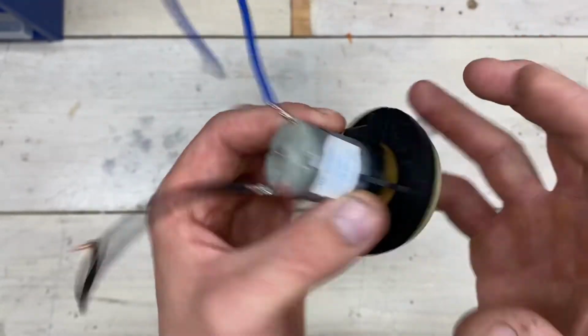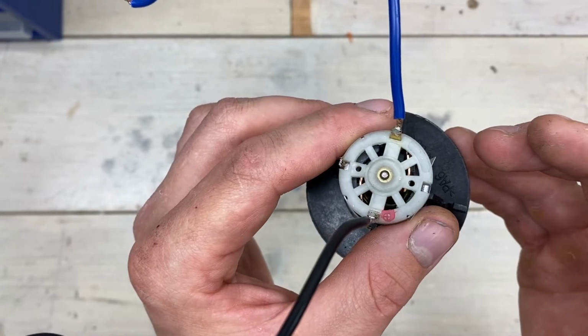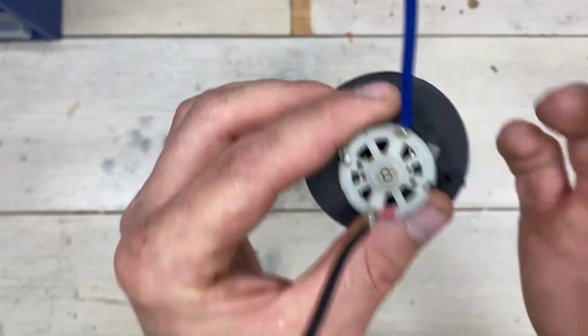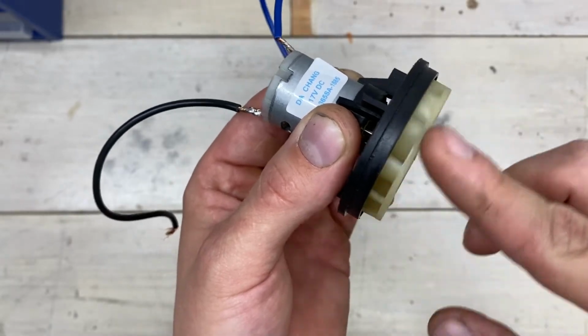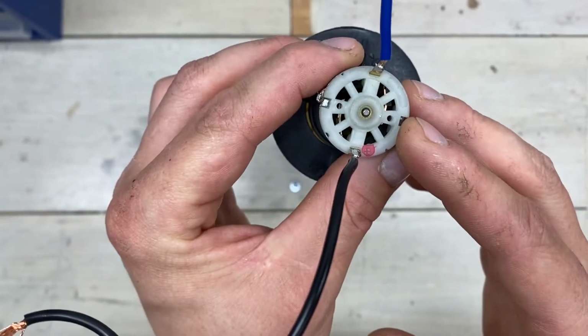But there's more to it than that. Within the rotor there are several coils, and each of these coils is turned into an electromagnet. Now there has to be at least three, there can be more as well, and the reason for this is because if there only were two coils, and we magnetize them, then the rotor would move to a stable position then stop. It wouldn't create any rotation. The part that the brush is connected to, I don't know how well you can see that, inside there, is called the commutator.